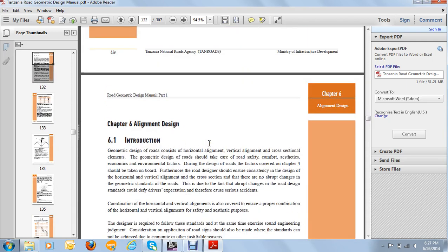So this is one of the parts, because at every stage of the road design, if we are designing our alignments, what should we consider? You should have a wide range depending on what type of road, whether you are creating on flat areas or in mountainous areas, or where there are embankments, and whether the roads are paved or unpaved. All those things should be considered.